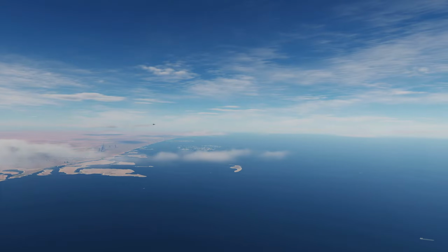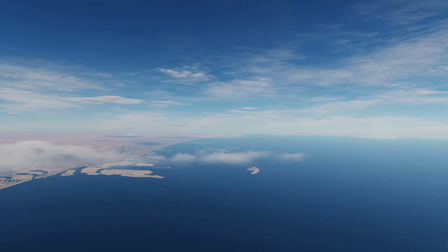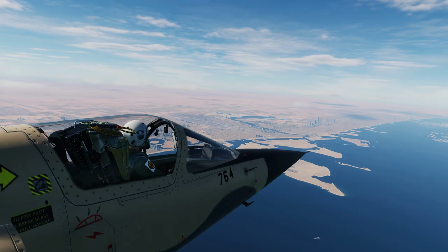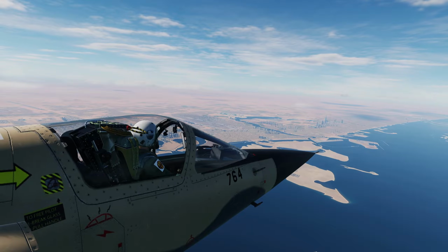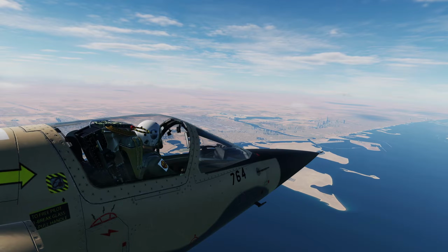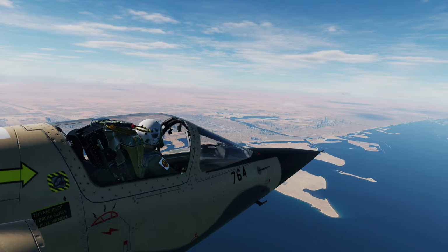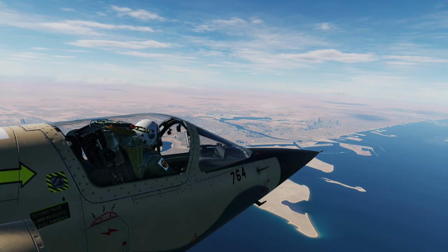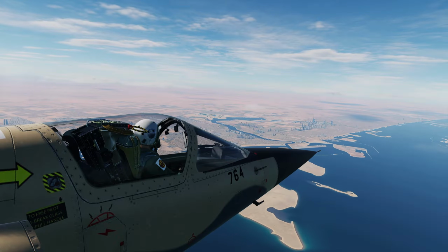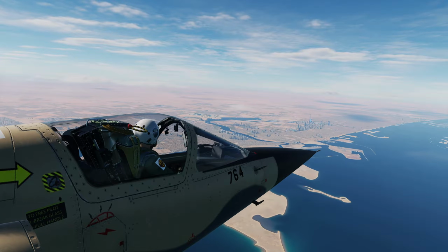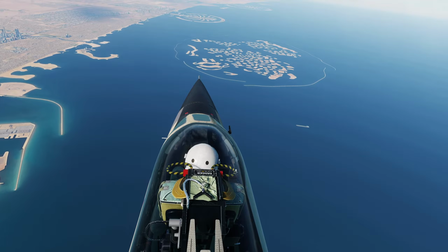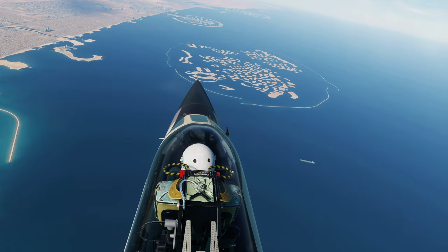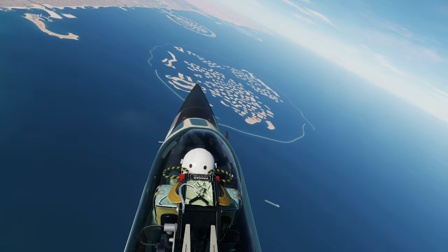A navigation offset allows us to find locations which are not marked, identified, or served by the usual methods available to us, for example an INS waypoint or a TACAN beacon. They do this by taking existing waypoints or beacons and mathematically altering their perceived position using some additional parameters. In the Mirage F1, this is done using the polar coordinate system, or more familiarly speaking, a bearing and a range.